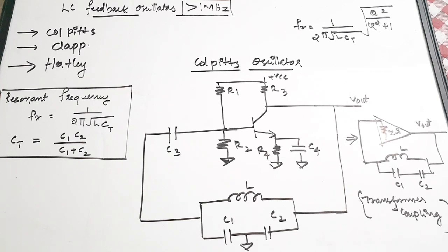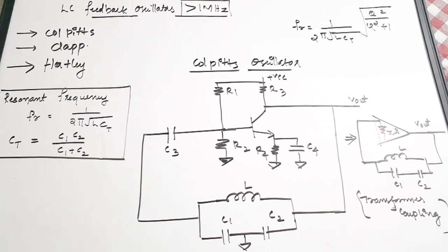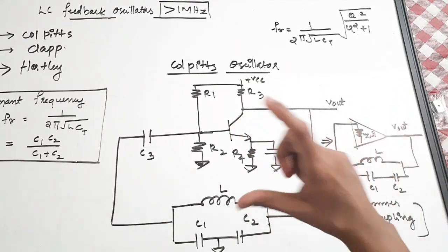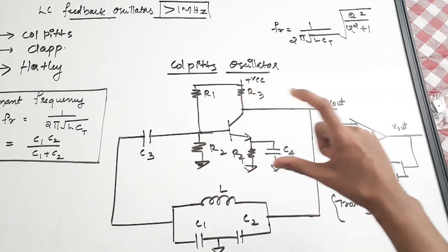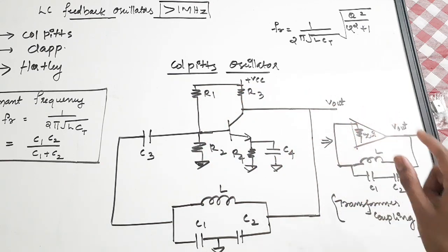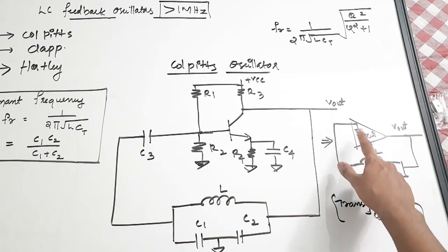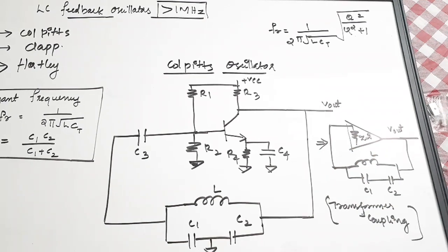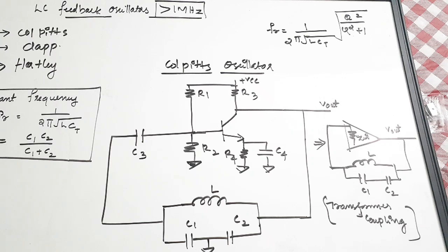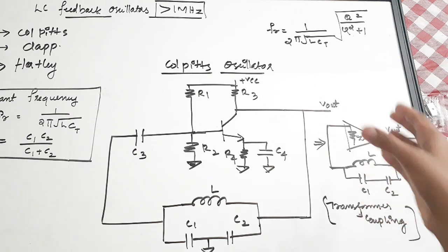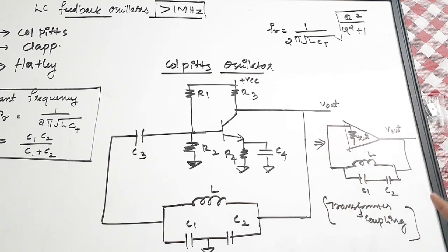And there is another thing you have to consider. Here, if you see, this is the equivalent circuit of this Colpitts oscillator, where we have represented the entire amplifier stage with a triangle which represents an amplifier. You can see there is a Zin written inside the triangle, which represents the input impedance of the amplifier, which is acting as a load to the feedback unit.